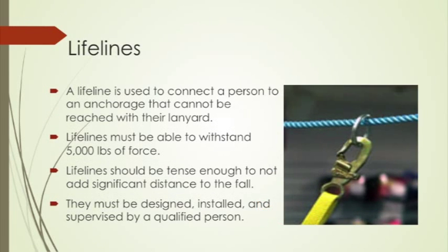A lifeline is used to connect a person to an anchorage that cannot be reached with their lanyard. Lifelines must be able to withstand 5,000 pounds of force and be taut enough to not add significant distance to the fall. They must be designed, installed, and supervised by a qualified person.